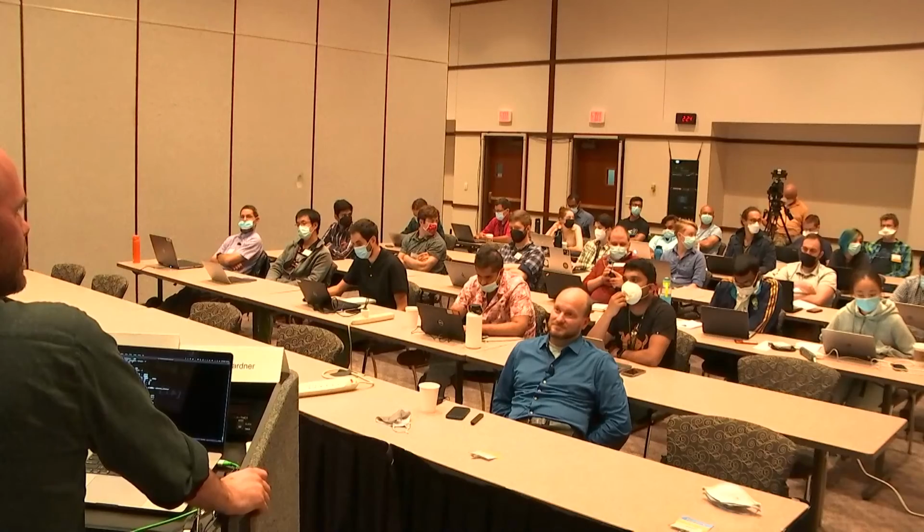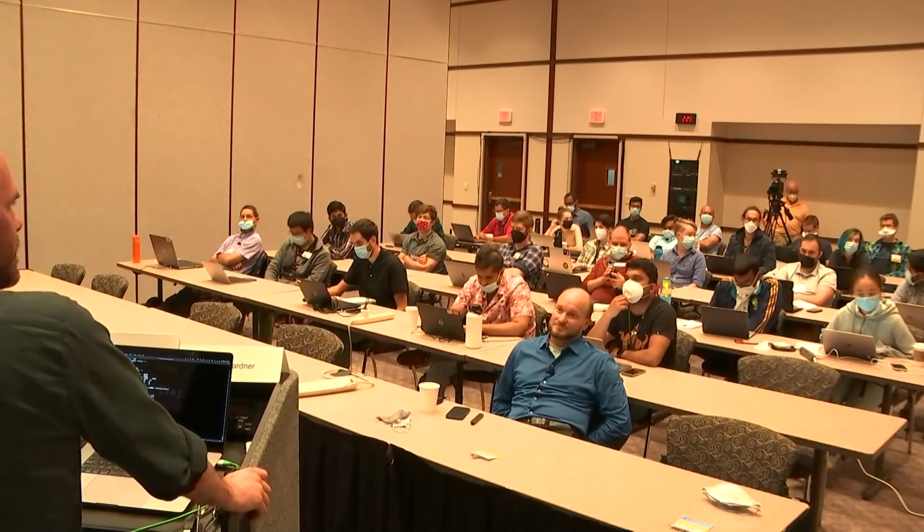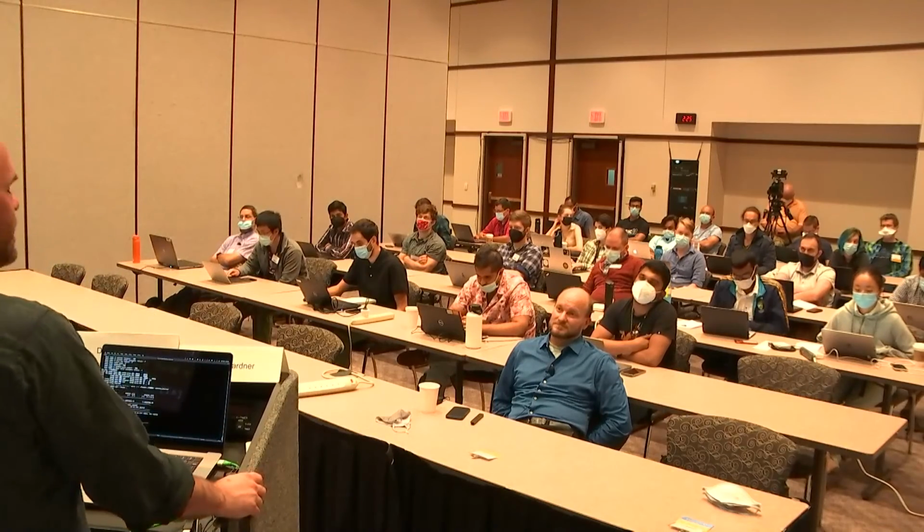Since it's using implicit methods, it's an implicit solver, so we can take a higher time step? Yep, exactly. So here we're using an A-stable scheme, so we're no longer bound by that stability limit. Here we're just worried about whether the time step that I'm going to take is accurate. I don't need to worry about that stability condition also.